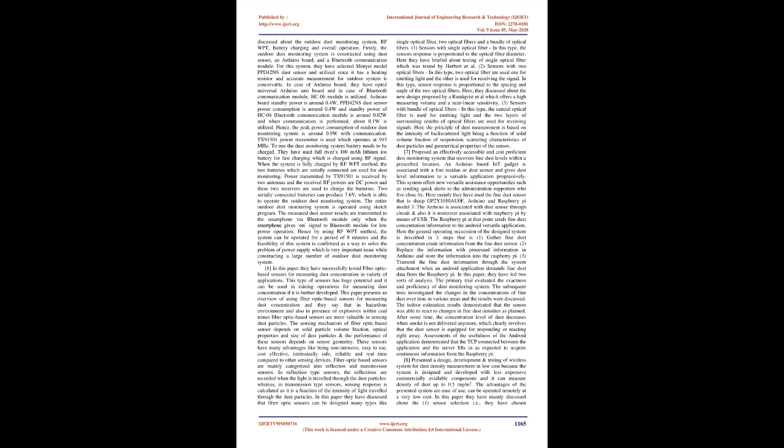In this paper, Powercast's TX91501 power transmitter is examined for its use in outdoor dust monitoring system. Here, they have briefly discussed the outdoor dust monitoring system, RFWPT, battery charging and overall operation. Firstly, the outdoor dust monitoring system is constructed using dust sensor, an Arduino board, and a Bluetooth communication module. For this system, they have selected Shinyei model PPD42NS dust sensor since it has a heating resistor and accurate measurement for outdoor system is conceivable.